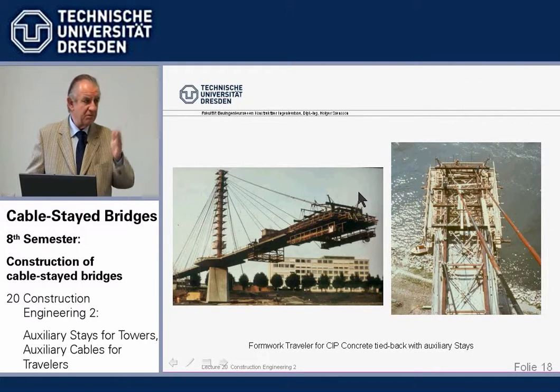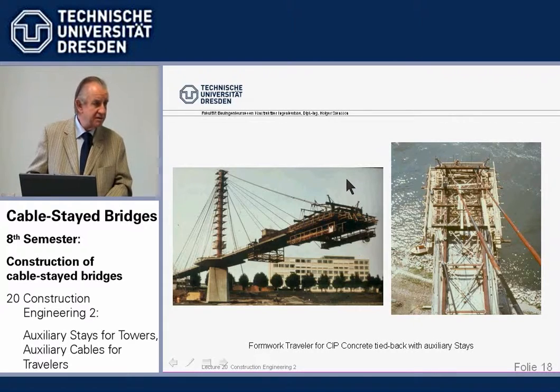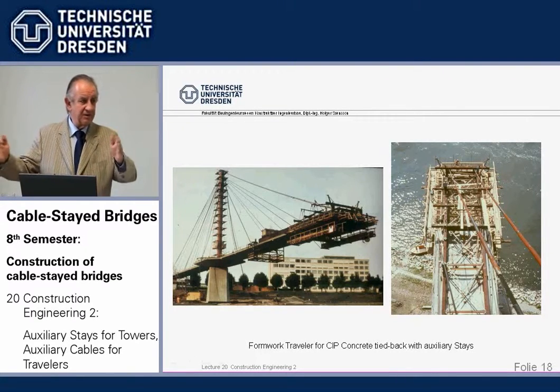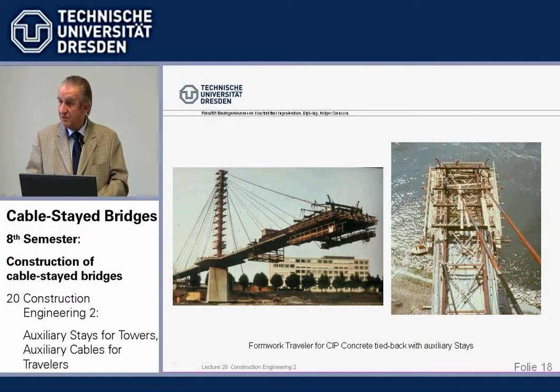That may be something like 10 meters, roughly speaking. And then depending on the depth, if we have only 1 meter depth of a beam, and cantilever that 10 meters, that's 1 in 10 for a cantilever. And there we realize already, maybe too much for the beam.